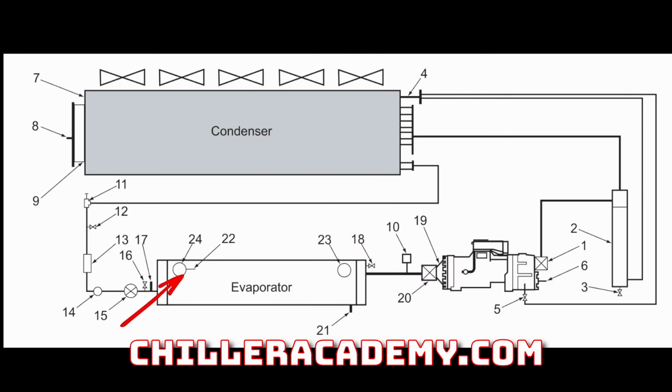So ultimately, we have our leaving water side. The chiller is going to register that our leaving water is not making set point, and so at that time, it is time to call on the chiller. We've already got start stop. We've proven flow. Pumps are running. All of that has happened. Our ambient is above our minimum for operation, so it's time to bring on the chiller. Now, it's time to bring the compressor on.